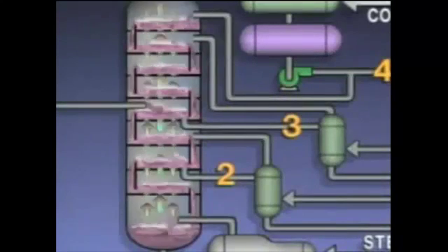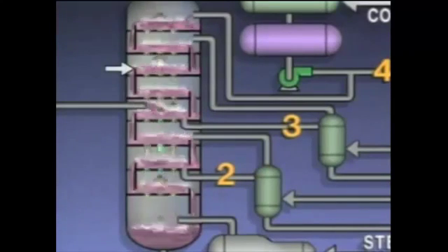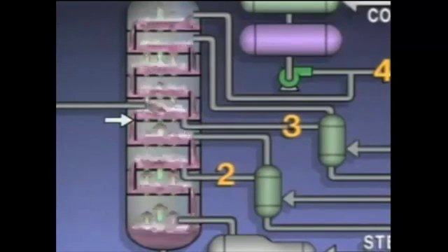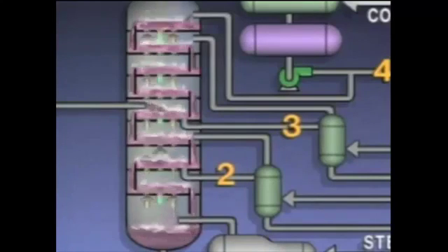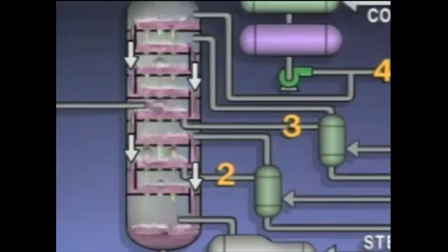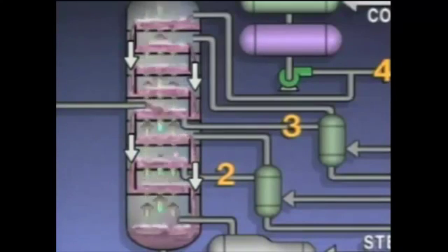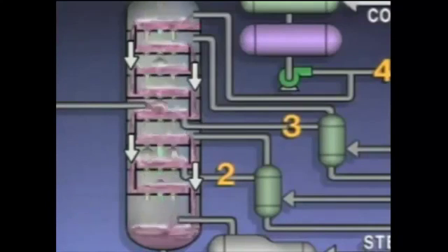The liquid in each tray in the tower collects to the height of a weir, which is a dam-like barrier that holds the liquid on the tray at a specific level. If the tray is at a draw-off point, a portion of the liquid is drawn off through a draw-off line. The liquid overflow from each tray is allowed to flow to lower trays through passages called downcomers. This liquid is called internal reflux. This arrangement helps to ensure that any heavier components of the liquid have a chance to travel down to their proper draw-off points.